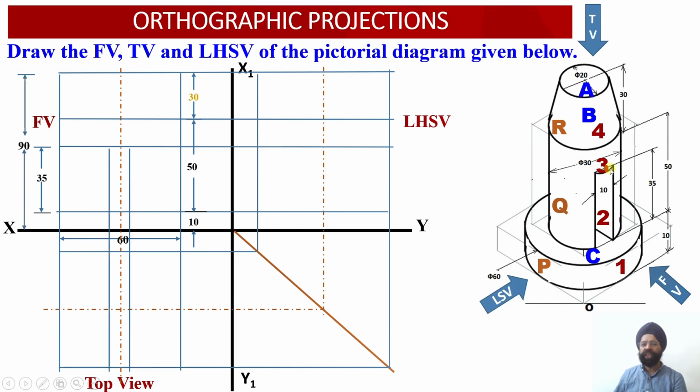Now having drawn these parameters, I need to draw this slot over here. What are the dimensions of this slot? Height is equal to 35 millimeter and the width of the slot is equal to 10 millimeter. So I have worked out the axis point or the midpoint along the width of this particular component. This is the center point along the width dimension.